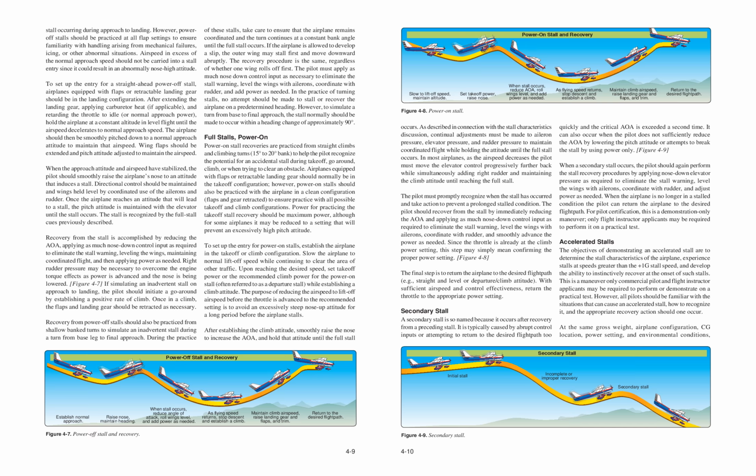It can also occur when the pilot does not sufficiently reduce the AOA by lowering the pitch attitude, or attempts to break the stall by using power only.